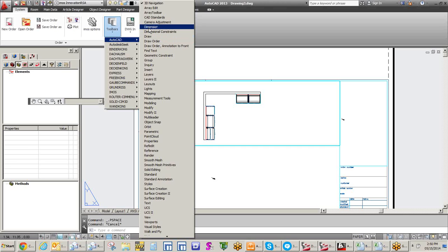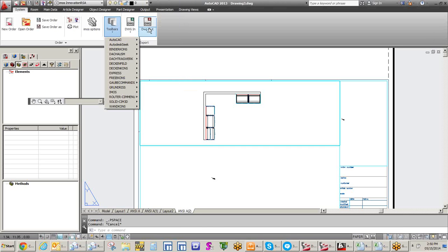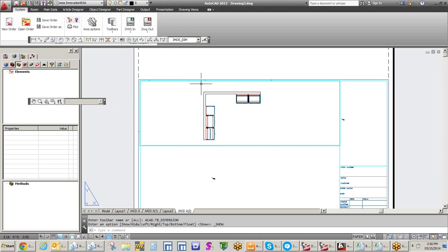You would never want this amount of cluttered stuff. So what you end up having to do is make flat shots of that actual 3D, which become dead. No, actually you don't. When I teach people, no, you don't. You're going to actually look at the live 3D. You just hide the lines beyond.